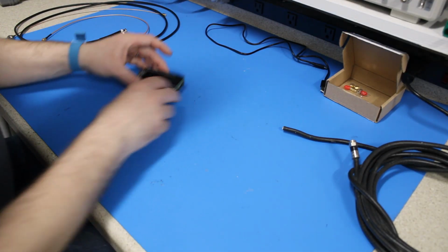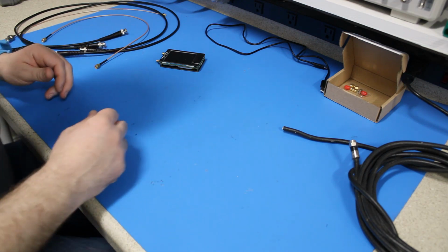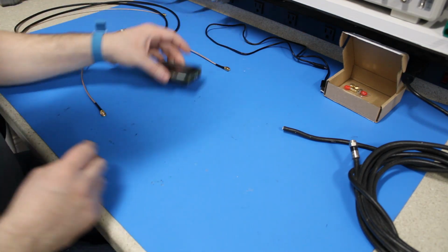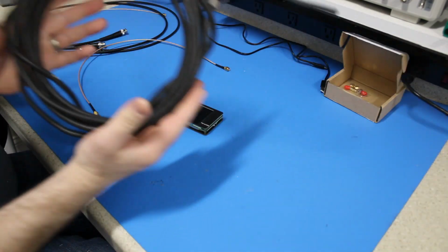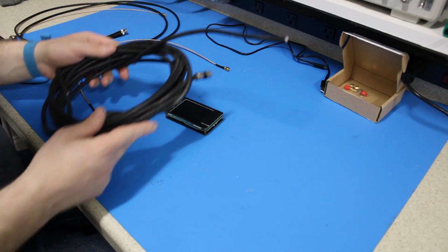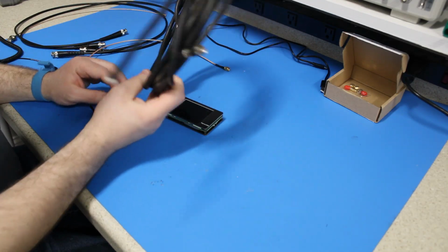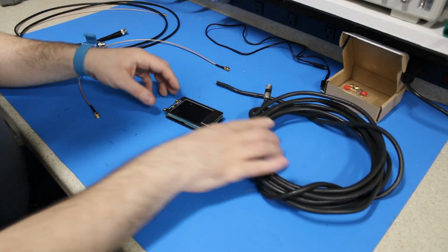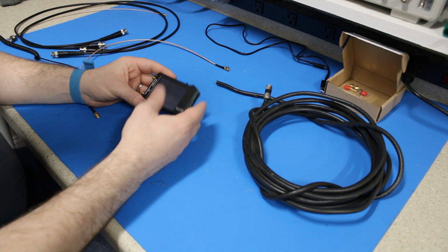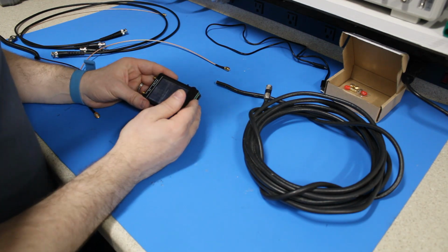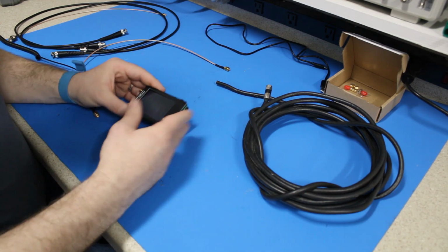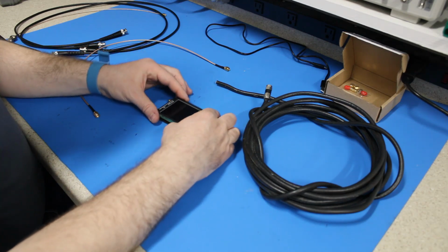All right, so those simulation examples are great, but what if you had a cable you wanted to do this on in real life? So we are going to take a cable here, just a random coil of 75 ohm cable TV coax that I pulled out of a bin. I have no idea how long it is. I haven't even unwound it, and we're going to use the NanoVNA here to take a phase measurement, and then we are going to use that in order to figure out what the length is. Then I'll uncoil it and I'll see how close we are.